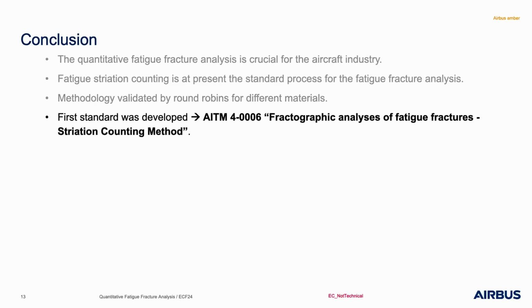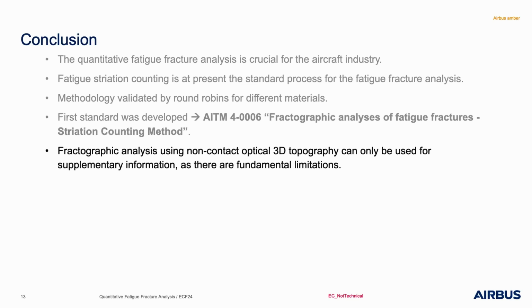From that, the first standard, as far as I know, the first standard within the industry is the Airbus industry test method, fractographic analysis of fatigue fractures, striation counting method. As I said, these 3D topographic measurements can only be used as supplementary information due to fundamental limitations.